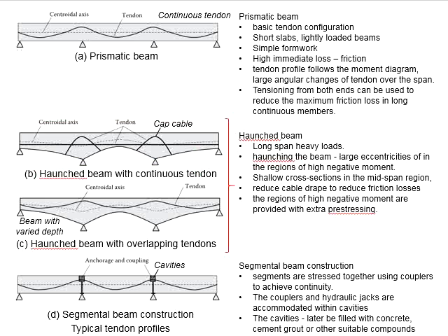This can still lead to the prestressing effects caused by the eccentricity. And you know that for normal conditions, we would like the members to have negative eccentricity. This is so that it generates resistance to counteract the negative moment at the intermediate supports.